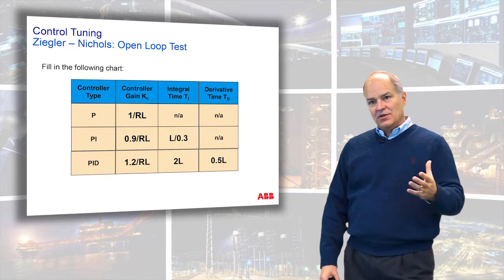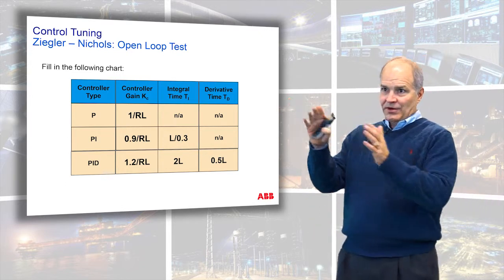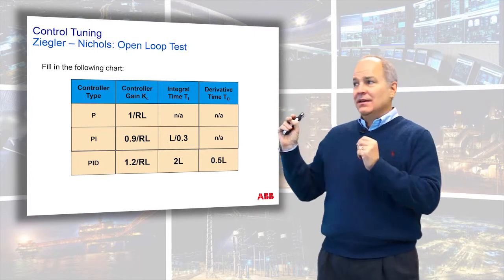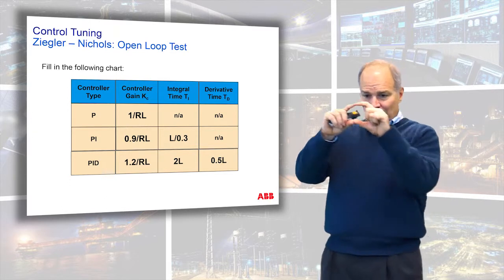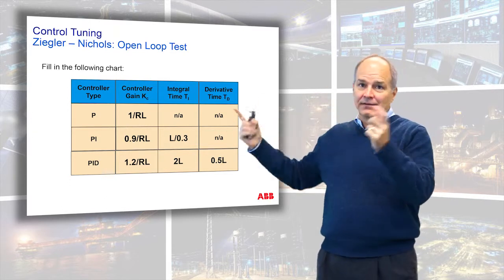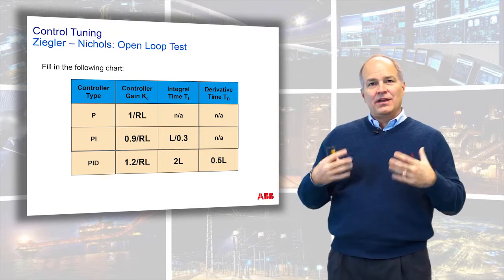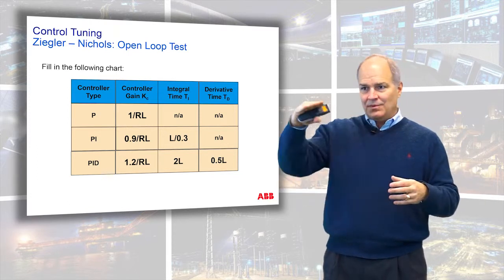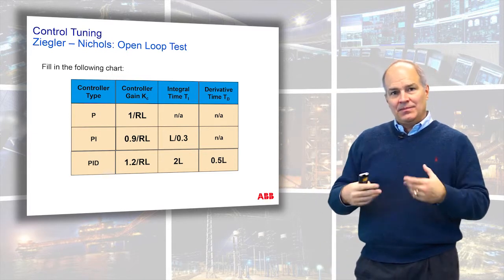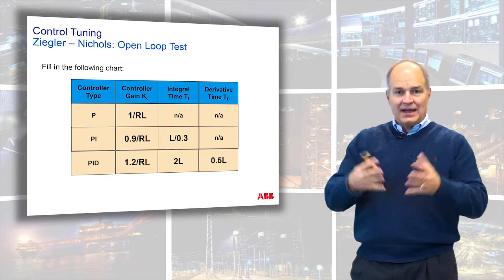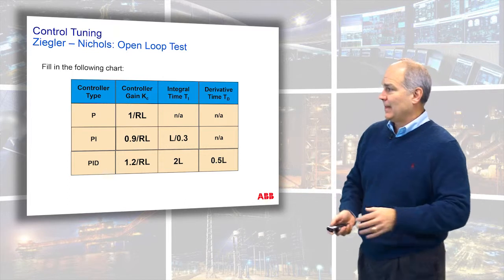Some industries are slow moving, or I will say that when you're doing tracking error, where you're trying to track a set point that's moving, this does produce the smallest, what they call velocity error. You can keep up with it. It's just when you stop, it's going to ring. That's the drawback. Direct synthesis is more designed the way industrial plants operate: set points, so it's more stable. You do one bump test, you look at the physics, and you can calculate the tuning parameters. So my bias is towards the direct synthesis technique.